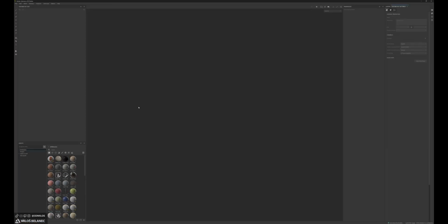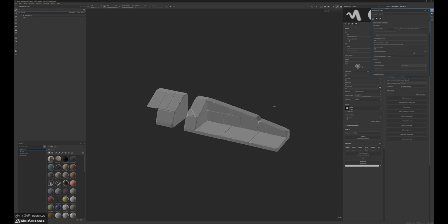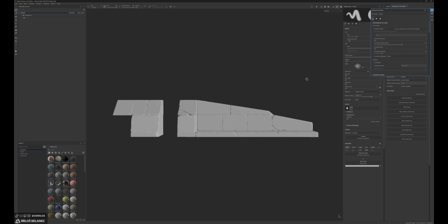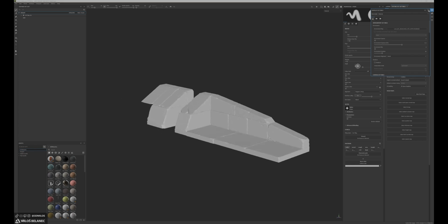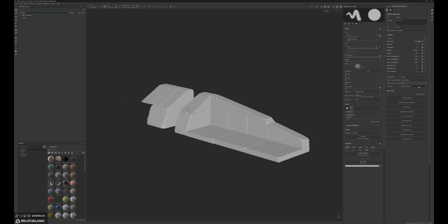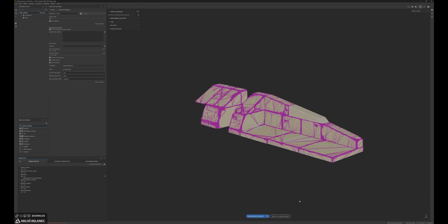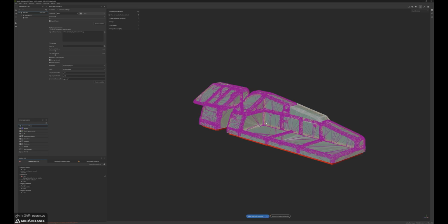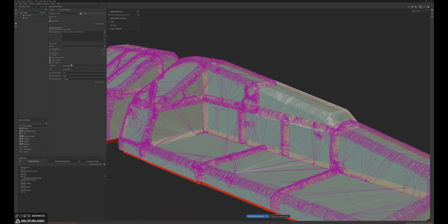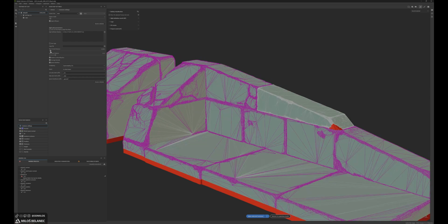Welcome to Substance Painter. You can check the mesh if everything is okay, all normals and all details, with Shift and drag the mouse or pen. Okay, everything looks good. Let's start with the baking. Uncheck this box. This is if you want to use the same model for baking the maps. Select the high poly model. Here is the cage for the distance, high poly and low poly.